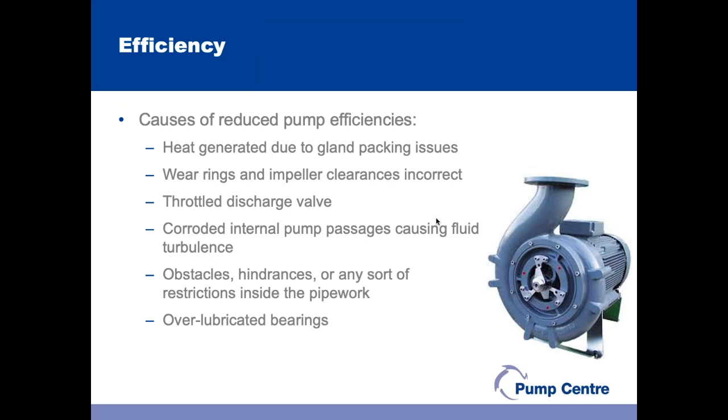You can have partial blockages, obstacles, valves partially closed. Any sort of restriction will tend to affect the performance of the pump and will reduce its efficiency. Another potential cause of reduced efficiency is over-lubricated bearings, and we'll look at that in a bit more detail in due course.